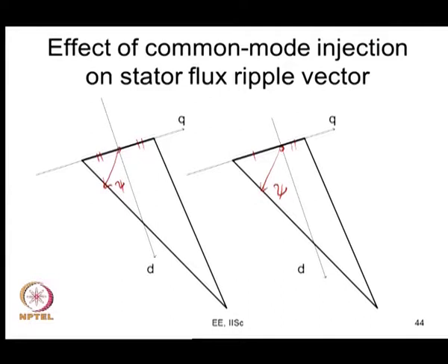So, conventional space vector PWM is better than sine triangle PWM and third harmonic injection except 1/4. Third harmonic injection 1/4 is similar to conventional space vector. So, it is better than those PWM methods now.